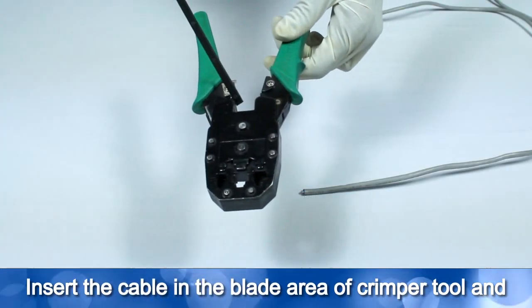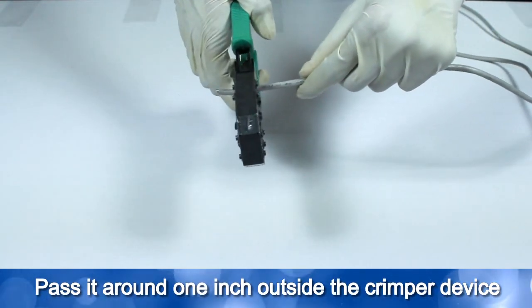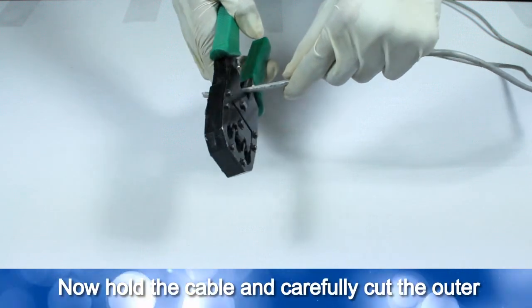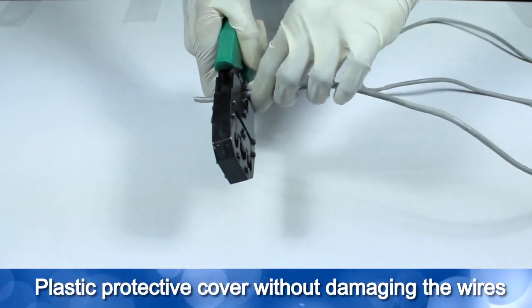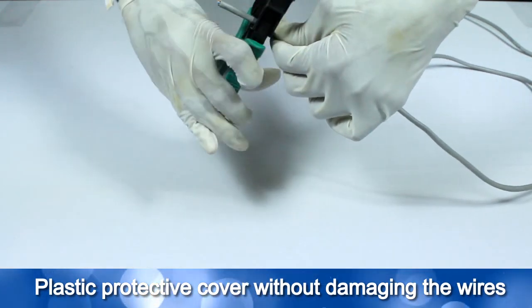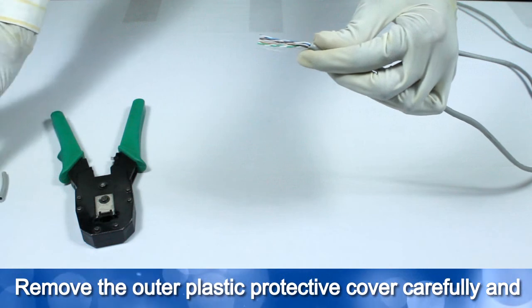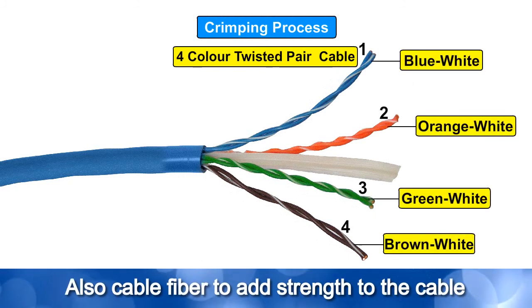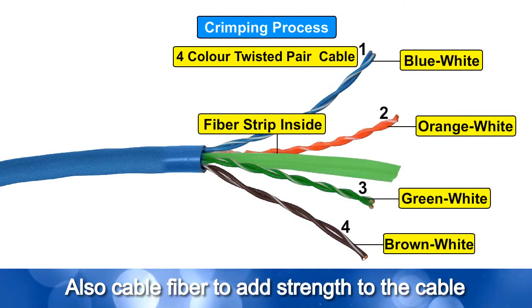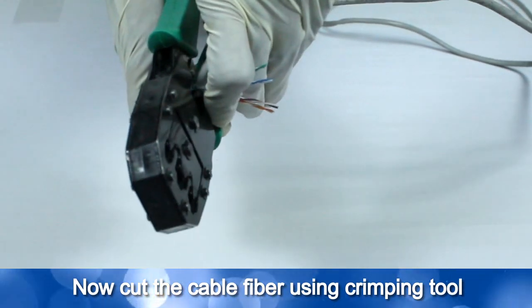Insert the cable in the blade area of the crimper tool and pass it around 1 inch outside the crimper tool. Now hold the cable and carefully cut the outer plastic protective cover without damaging the wires. Remove the cover carefully, and now you can see 4 pair twisted cable and also cable fiber to add strength to the cable. Now cut the cable fiber using the crimping tool.